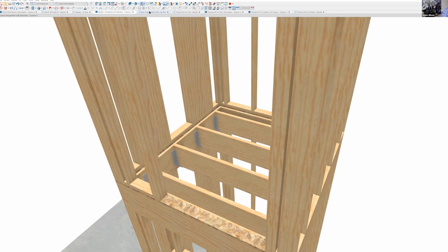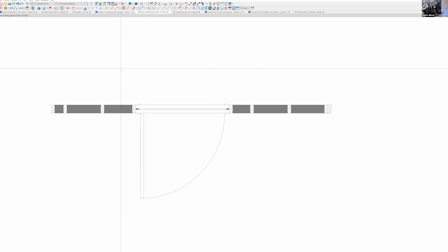Another little trick I like here, typical wall with a door, and Chief is really great at adding the framing members. Usually they're pretty good just being inset or created automatically, and I think that is what I did in this case. But then I went ahead and modified this wall framing. But here's the thing: when you're doing a building that may at some point require a wheelchair or some kind of wider opening, it is quite expensive to go in and tear out a wall in order to do that. But it's so easy to just go ahead and plan for it in advance.